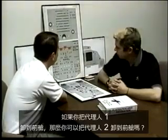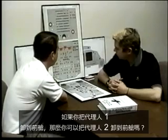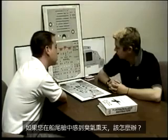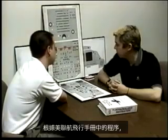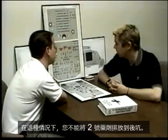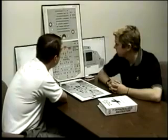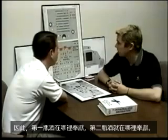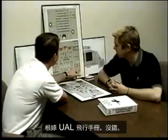If you discharge Agent 1 into the forward cabin, can you discharge Agent 2 in the aft if you were to get smoke in the aft cabin? According to the procedures in the United Flight Manual, you cannot discharge Agent 2 into the aft pit in this case. So wherever the first bottle is dedicated, second bottle is dedicated. According to the UAL Flight Manual, that's correct.